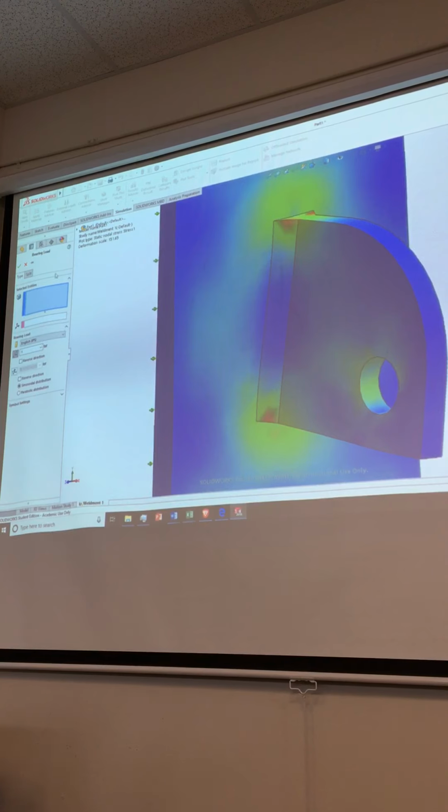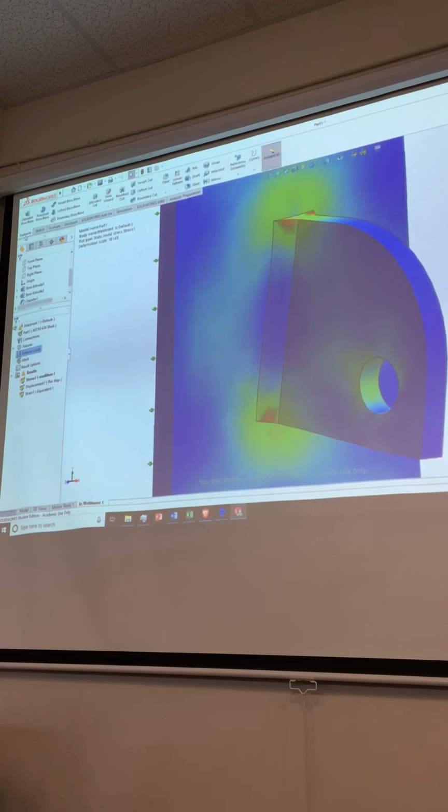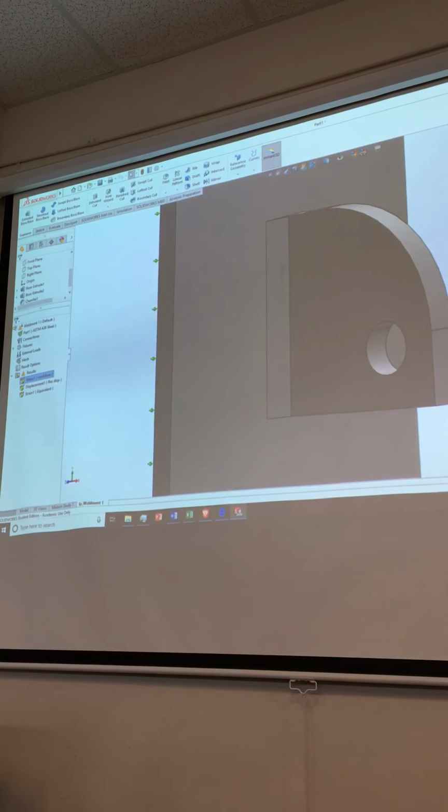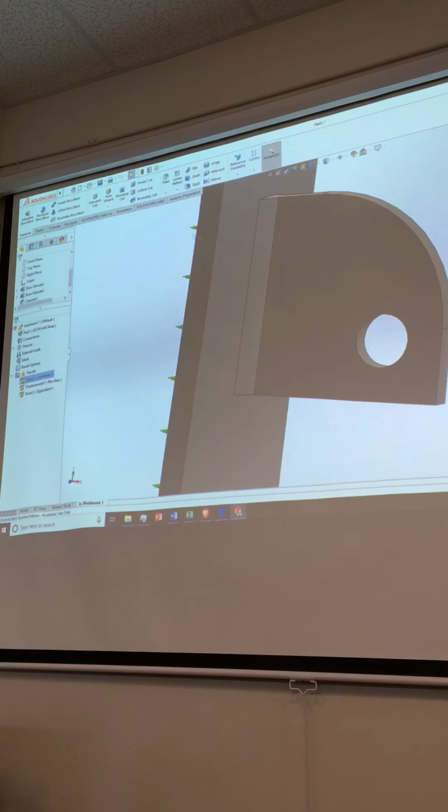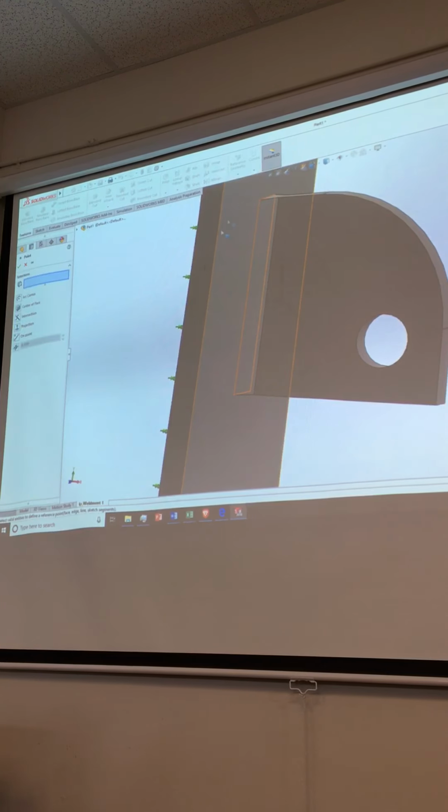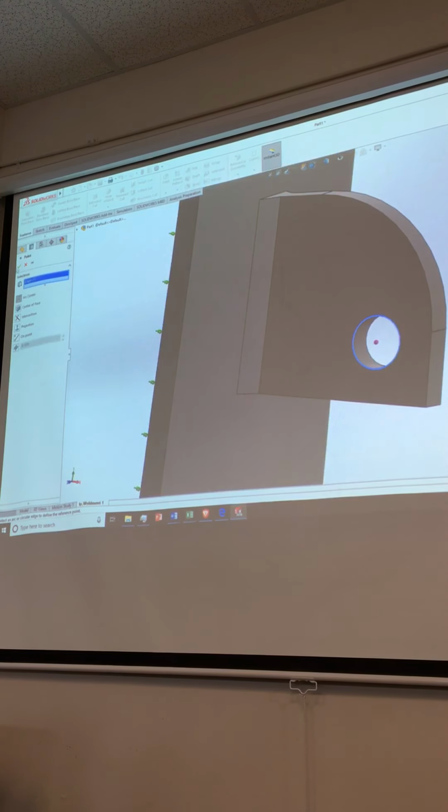Oh, well, go back to the features over here. Let's go hide this guy, right? So there we go. We'll go back to this guy over here. And now we've got to do reference geometry, right? We need a coordinate system. In order to make a coordinate system, I need a point. So we start with a point. Okay, how do I want to make a point? How about some arc center? Right, okay, how about the center of that thing there? Doesn't like it, center of that one there, that's fine. Give me a point, center of a circle, that's a fine point.